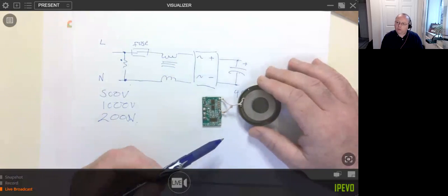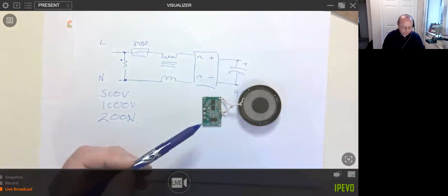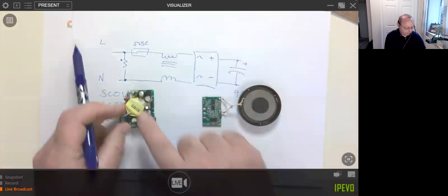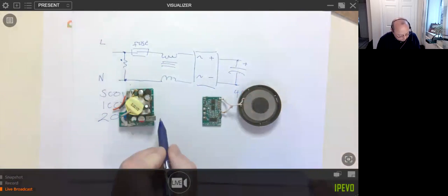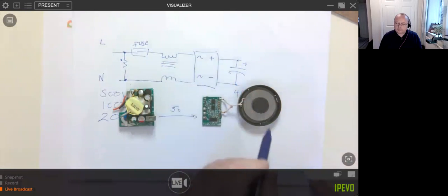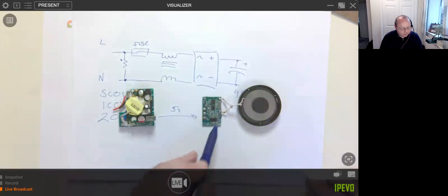You'd think there's not a lot on this. So they have the 5 volts coming to where I'm pointing here, comes in here from our slightly zapped charger. The mains comes in here on this red and black, comes across to here. I could draw it on actually, couldn't I? There we go, 5 volts. And then this is magnetically coupled for wireless charging. So this tiny board here has absolutely ruined a lot of my EMC work.